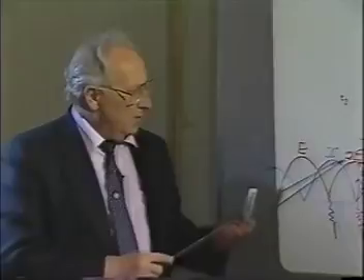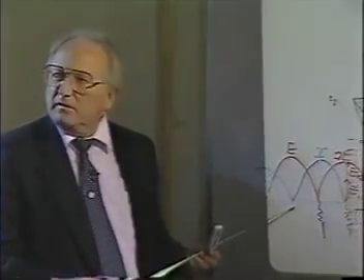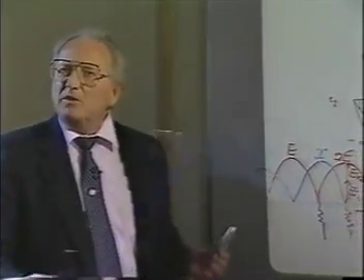Minimum. When the voltage is maximum, what is the current? Minimum. That's always going to be the case with a standing wave pattern. Where the voltage is maximum, the impedance is maximum. Where the current is minimum, what's going to happen here? The impedance has to be a minimum.